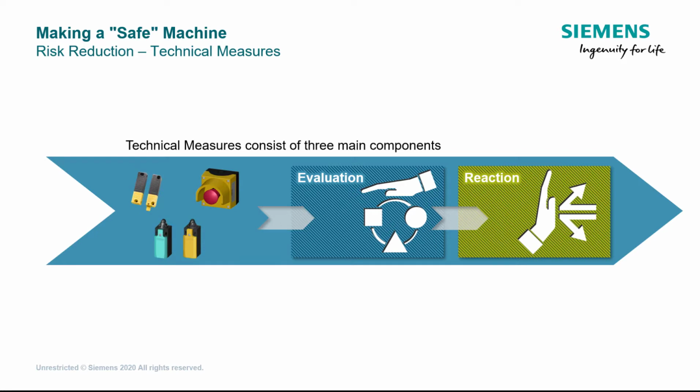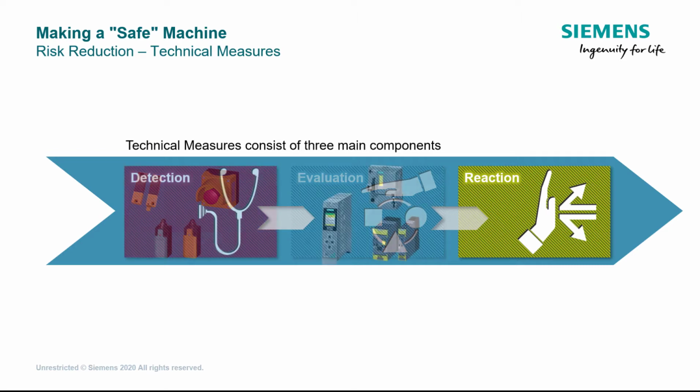In the detection phase, this is where monitoring of conditions on and around the machine can be accomplished by way of an e-stop, gate switch, safety mat, or possibly maybe a light curtain, for example. All detection is wrapped around detecting the hazardous situation.